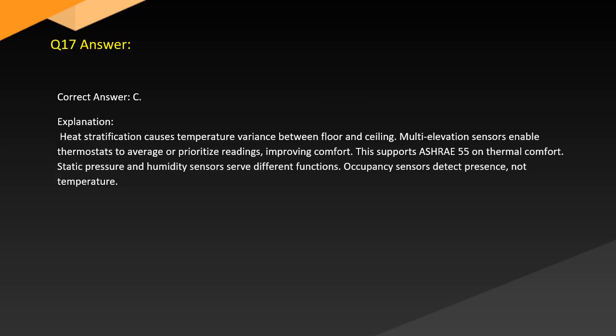Answer. Correct answer: C. Explanation. Heat stratification causes temperature variance between floor and ceiling. Multi-elevation sensors enable thermostats to average or prioritize readings, improving comfort. This supports ASHRAE 55 on thermal comfort. Static pressure and humidity sensors serve different functions. Occupancy sensors detect presence, not temperature.